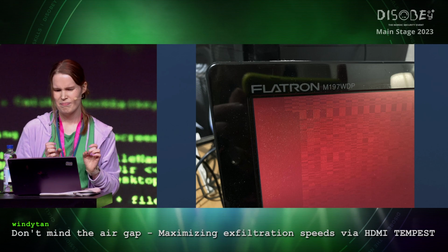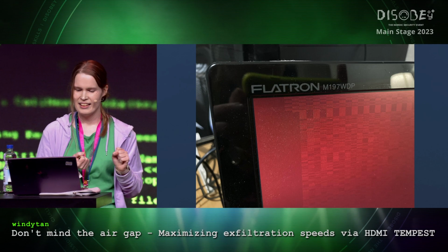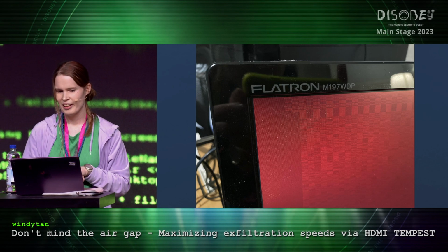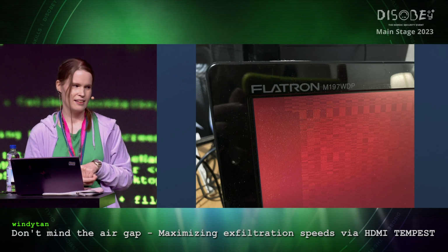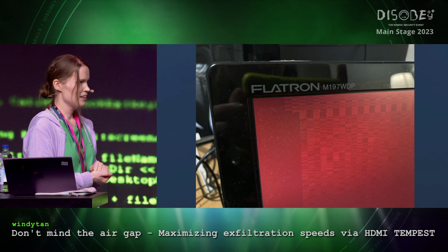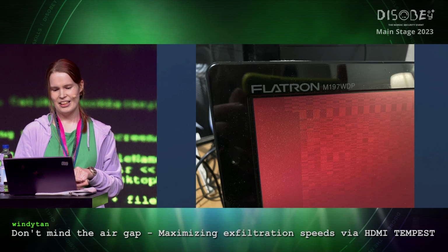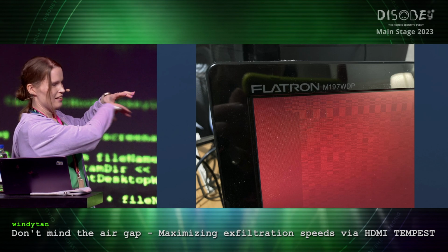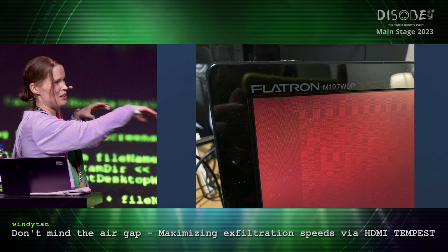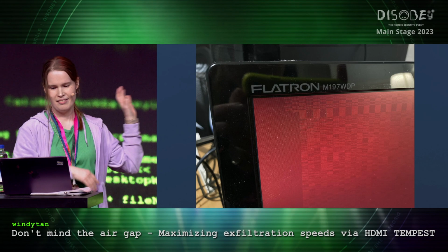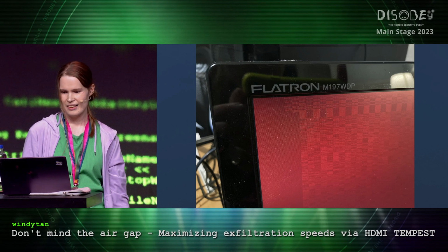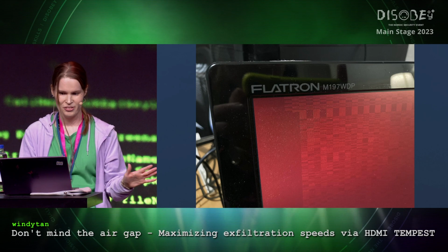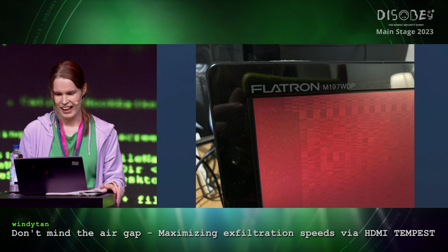And there's one more irritating thing. The Raspberry Pi 4 that I was using doesn't really play nicely with VSync video, so there is a bad tearing effect. And whenever there is tearing, it always goes straight through the image horizontally and breaks every packet. So I get zero data at all. Eventually, later, I redesigned it and made it horizontal.